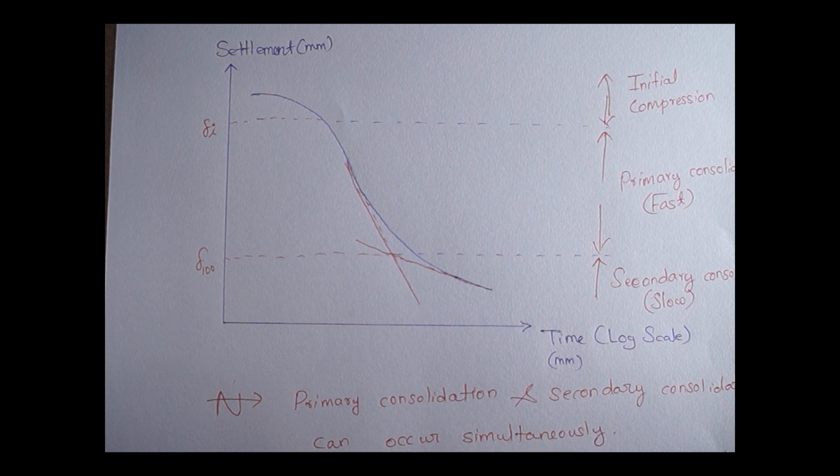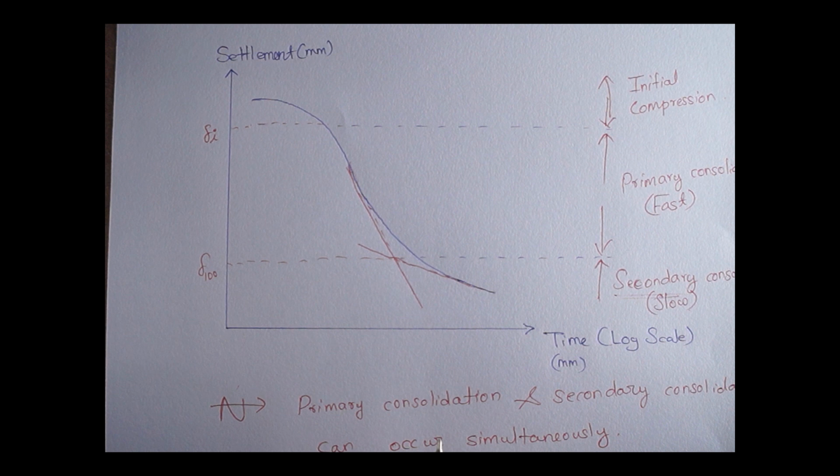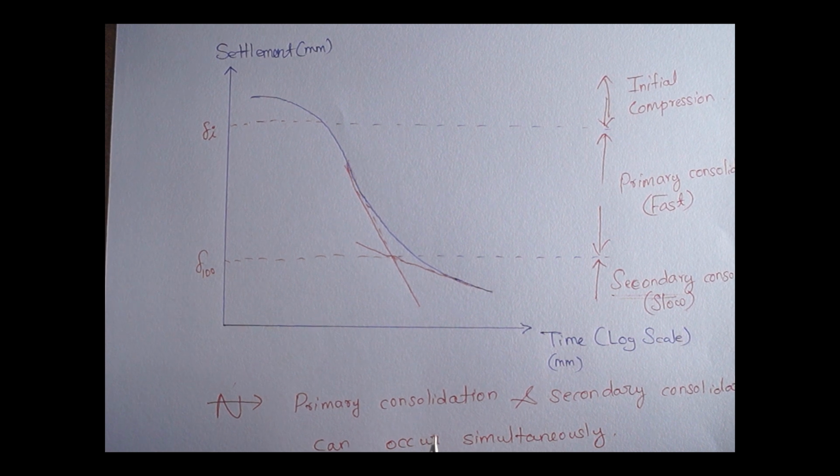So before ending of primary consolidation, the secondary consolidation process begins. So it does not mean the primary consolidation process has to completely end before starting the secondary consolidation process. So we should remember that that is an important point.